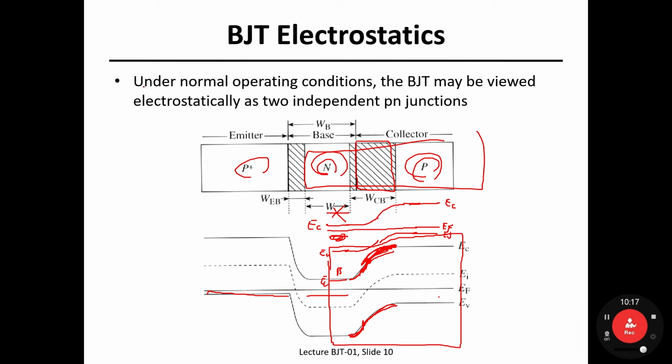And again, since the BJT is operating in active mode, the emitter base PN junction should be forward biased, and the base collector PN junction should be reverse biased. Usually the active mode is the preferred one for signal amplifier applications.